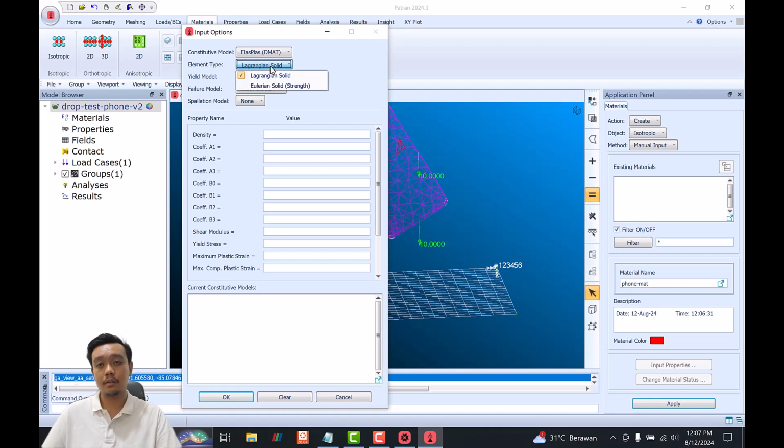And one thing that you must understand in Dytran is it uses two solvers, which are Lagrangian and also Eulerian, so you can easily couple the simulation between the structure and also fluid effortlessly without a computational fluid dynamics solver, let's say. So it is a very robust solver to solve things like explosion or maybe underwater explosion or maybe crash involving airbags of flow, and that kind of thing.